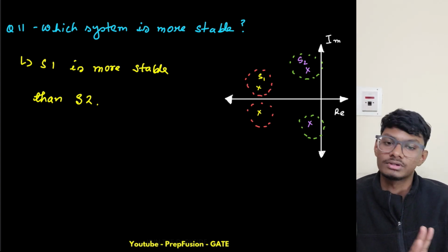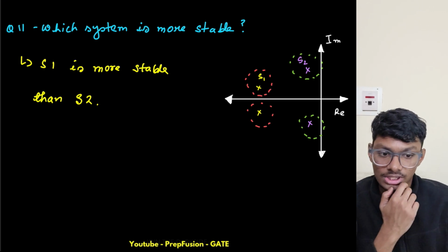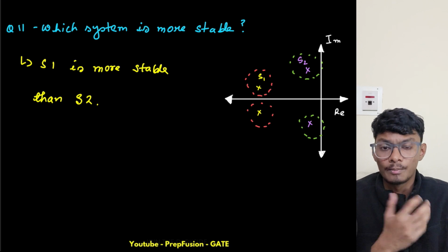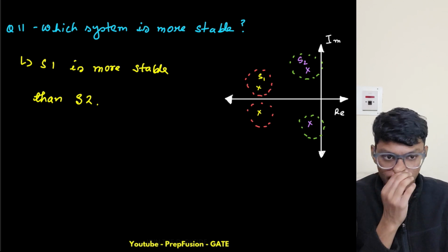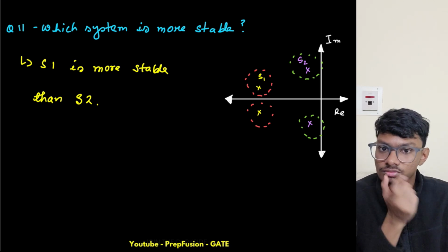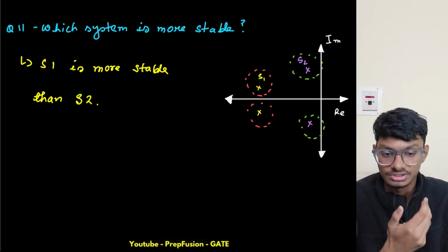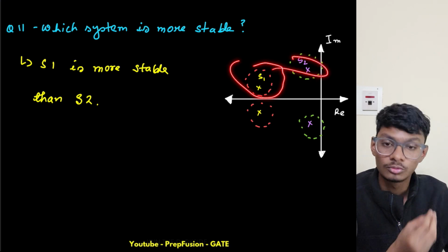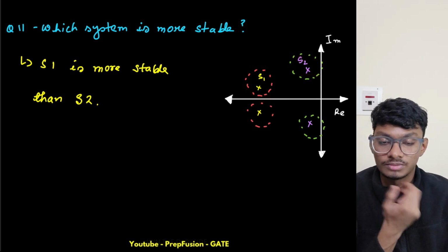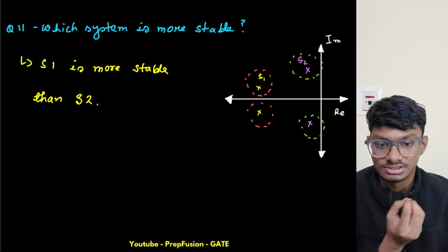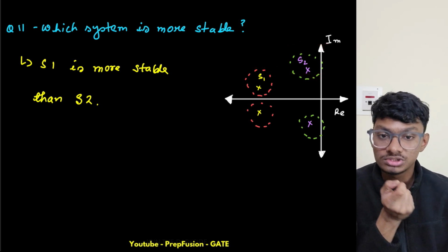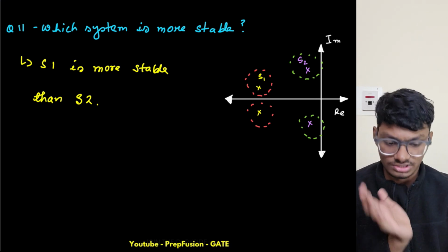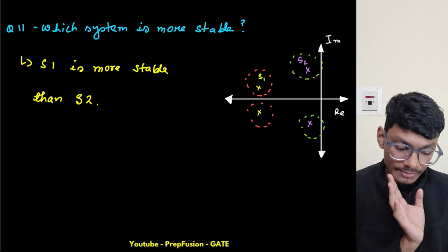But I have to compare two systems and choose between them. As a control engineer, I have been given two systems and I have to tell which one I should choose. For that I have to define some parameters, like the time domain parameters and the stability factor as well. Why does this happen? Due to parametric variation, practicality, non-idealities. My poles may not lie exactly at this point; they may vary due to temperature variation or whatever, so that may occur.